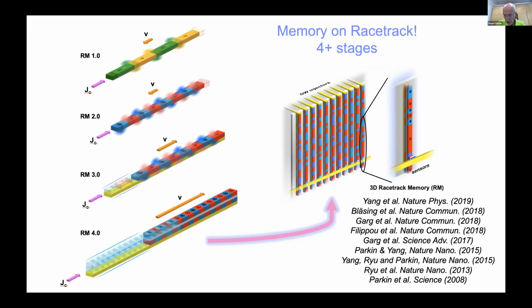And the concept is, on the nanoscale, the dipole fields become so large that they cause interactions between layers within a vertical stack, or in this case, from one domain wall to the next one. And we've demonstrated, at least by simulations, that if you do not use this synthetic antiferromagnet, but just use a ferromagnetic layer, as shown here in racetrack 3.0, then neighboring racetracks cause interactions between the domain walls through dipole fields and cause the domain walls not to move reliably. So the synthetic antiferromagnetic racetrack is super important, and that's something that we demonstrated in 2015 in this Nature Nano paper.